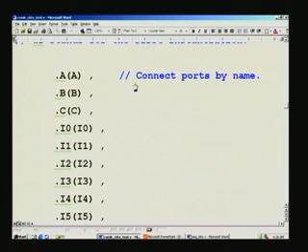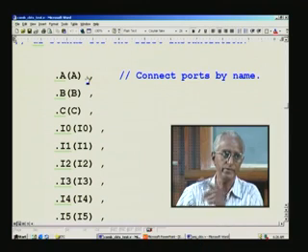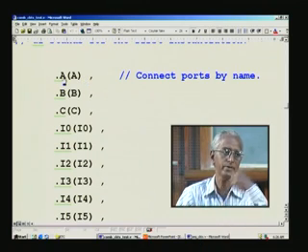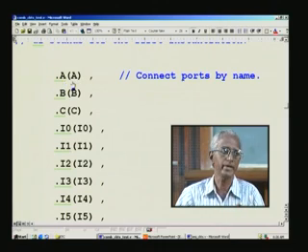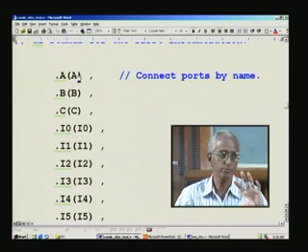Okay. So, how you connect the name is you use a dot here, and these two need not be the same. This means within brackets you are implying the A signal is within this test bench. Are you very clear about this? What is covered within brackets is within the test bench, not in the design, whereas this means this is the nomenclature adopted in the design. So, that is how you tie between the various permutation combinations.